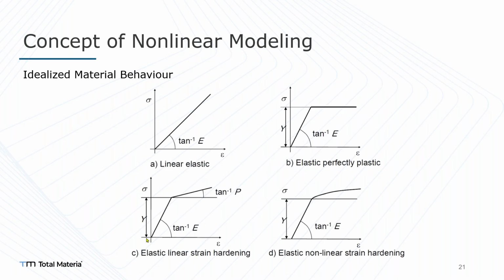Yeah, and the elastic to plastic area can cause a nonlinear material convergence issue. There is actually a common mistake with elastic perfectly plastic materials. As you can see, there's too much stiffness in here.